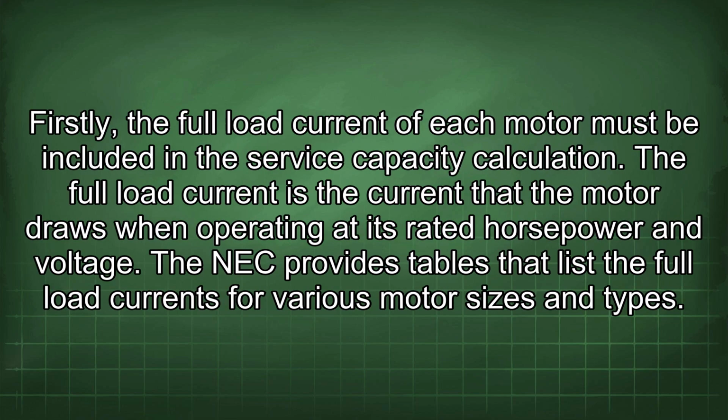Firstly, the full load current of each motor must be included in the service capacity calculation. The full load current is the current that the motor draws when operating at its rated horsepower and voltage. The NEC provides tables that list the full load currents for various motor sizes and types.